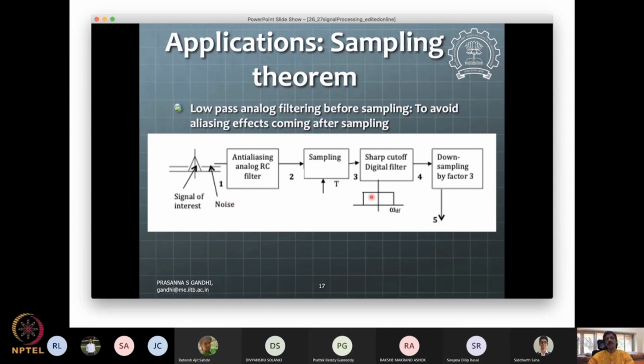You will say, oh no, this downsampling may not work. I will downsample only by a factor of 2, or I'll have to cut off at a much lesser frequency so that this downsampling does not produce aliasing. That kind of thinking is what I'm calling engineering that needs to be done. So the fundamentals for that are all there.